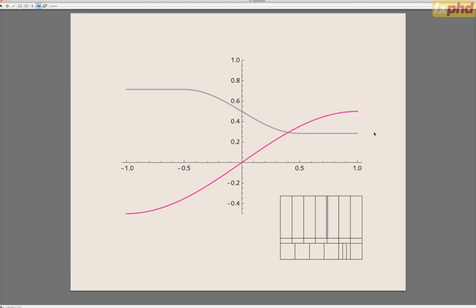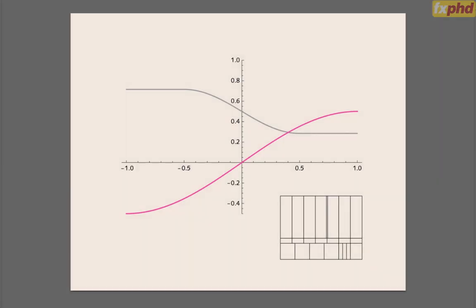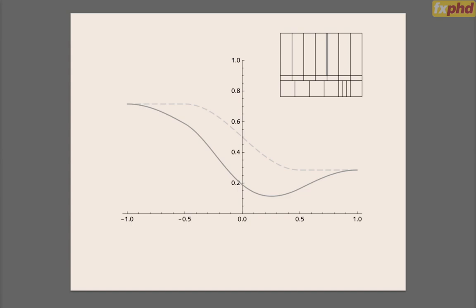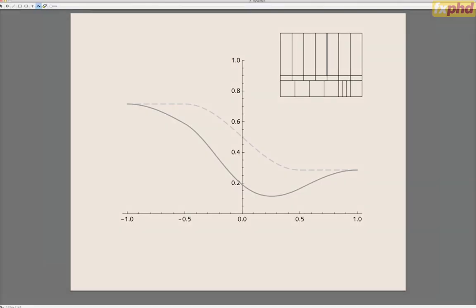This is what the signals look like in the electronic domain, but when you do the color science, what happens is in the optical domain, for certain color transitions, the luminance is not produced correctly at the display. And here I'm showing you a classic example of the transition from the green color bar, and I'll color it for you now, and the magenta color bar. And between those bars, there's a dip that takes place in the luminance. So the true Y, the color science Y, dips. And this is not an optical illusion. This is actually the luminance physically being reproduced incorrectly.